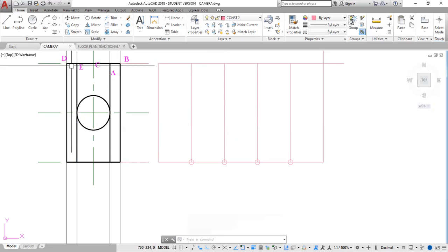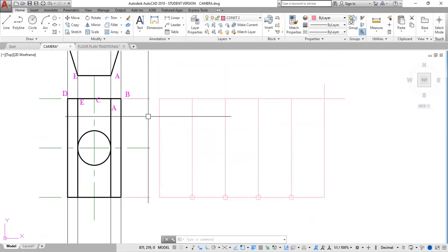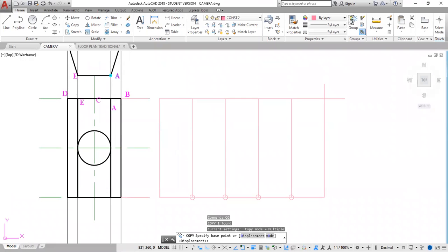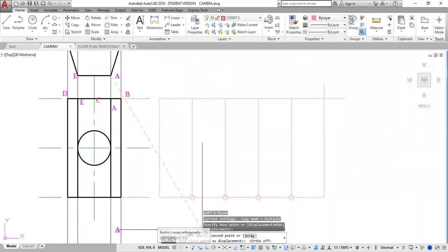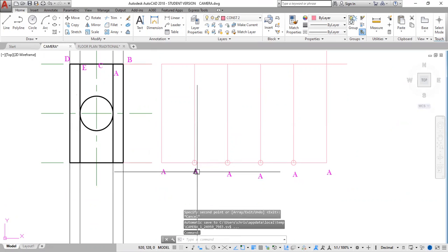So it's good to label these, right? So to label these, the question did not specify where we should cut the drawing. So I'm gonna cut the drawing at point A right here. So I'm gonna copy this, CO, enter, specify the base point here, and I'm gonna drop 1 here, 2, 1 there, 1 there as well, escape. Then click 2 times, 1, 2, wait a bit.